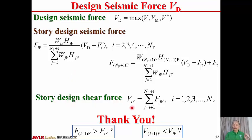Vi^F is equal to the summation from j equal to i plus 1 to N^F plus 1 of Fj^F, and i equal to 1, 2 up to N^F. Therefore, the design shear force of the i floor equals the summation of the seismic force of all the floors above the floor.